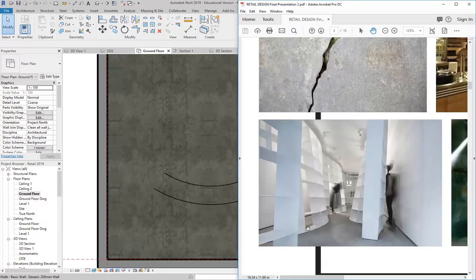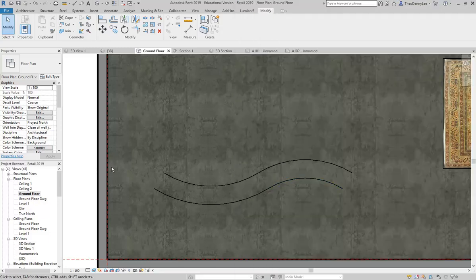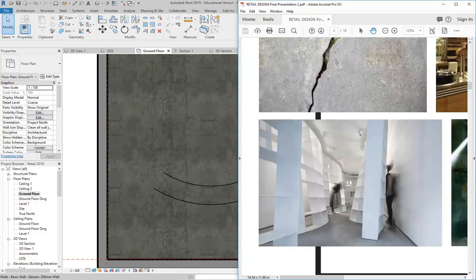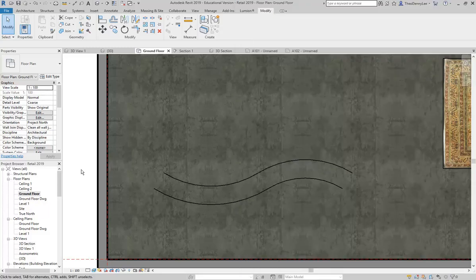In fact, that's probably too much. Looking at it again, they're not that deep, but 400 is a nice depth for shelves, so I'm going to keep it at that, even though this one looks like it's probably about 300. So that's going to give me the basis for my first extrusion for the shelf on the bottom. In fact, if we've got a shelf, yeah, we do have one. That's a bit unusual, but they've got a shelf that sits on the floor. It's not typical, but that's how they've done it, so I'll do that too.